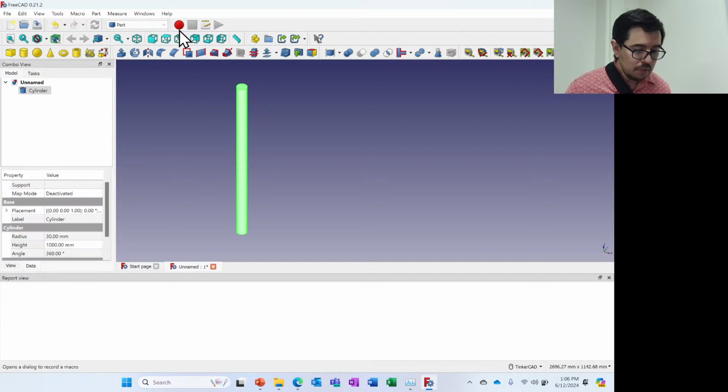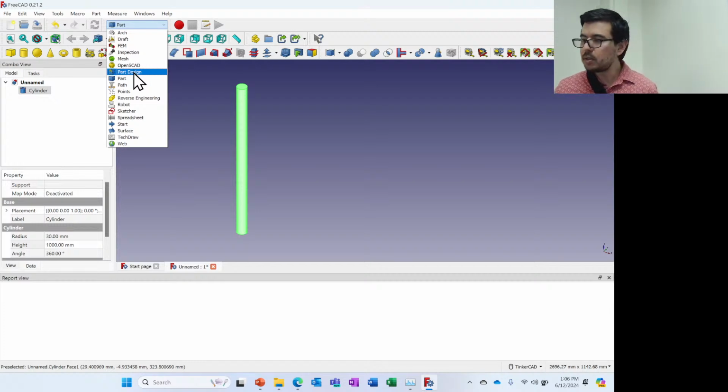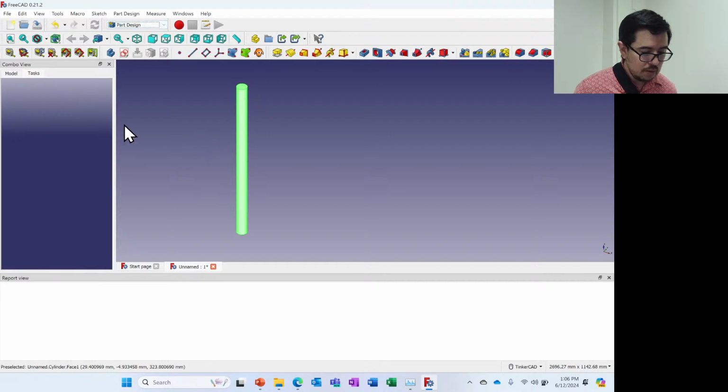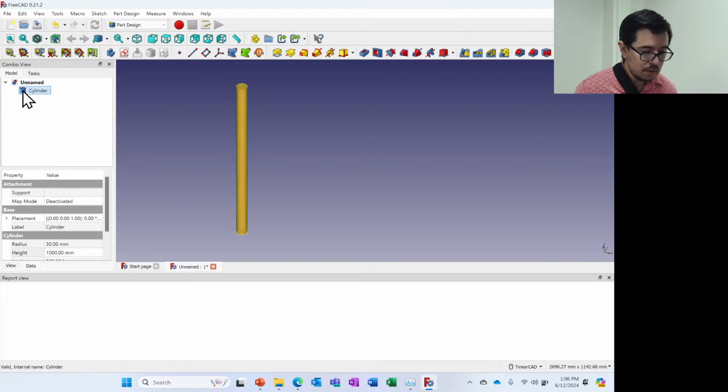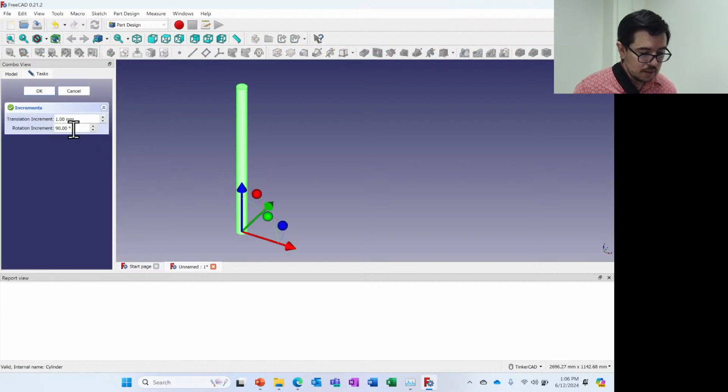Okay. Sometimes I've had issues with translating between the coordinate axes in FreeCAD and PrePOMAX, but if you like to rotate your cylinder, you can go to Part Design, go to the model tree, click on the cylinder, right click, and do a transform. I think it defaults to 15-degree increments, but you can put it in at 90-degree increments.